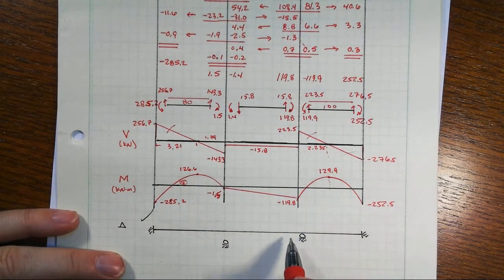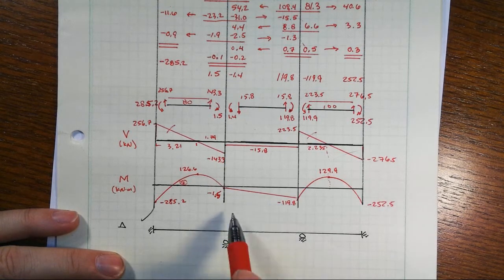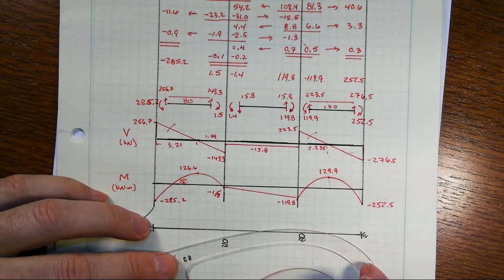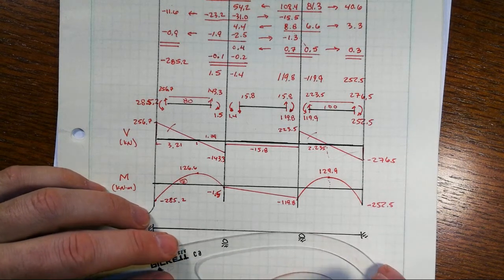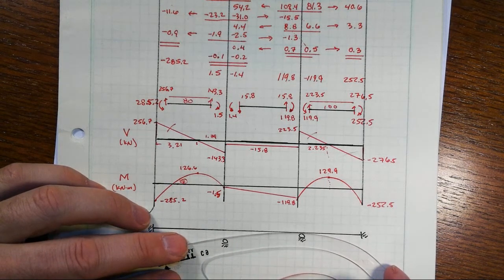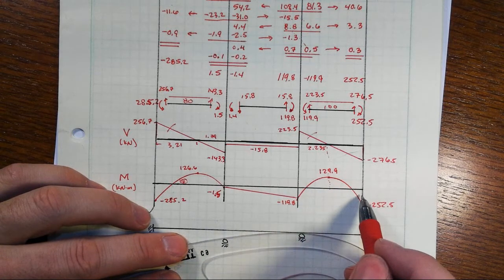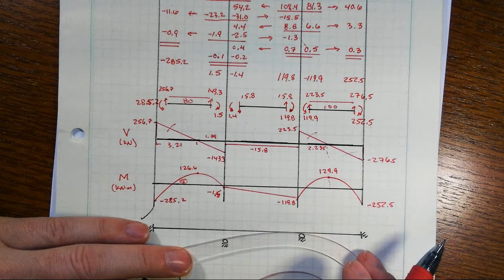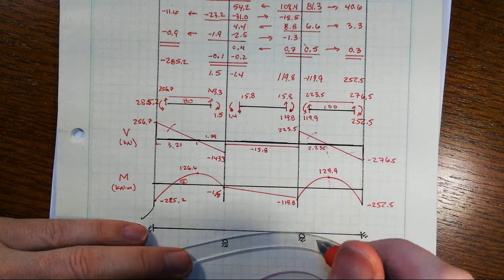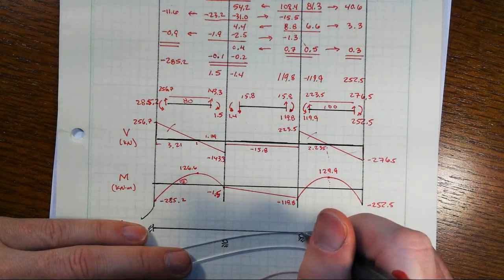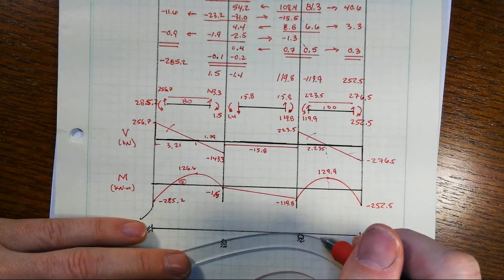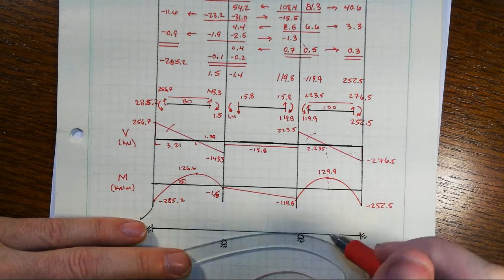Right, so now we go look and we say we got negative curvature here in the middle. That means the only way that can fit in there is something of this kind of nature. We've got frowny face, positive face, frowny face, so looks to me like we're going to have something that nearly zero rotation here, or even at joint C probably a clockwise type rotation to ever begin to try to make this work.